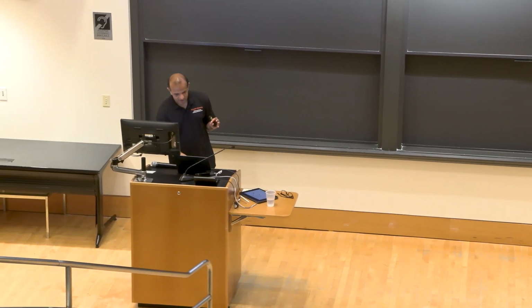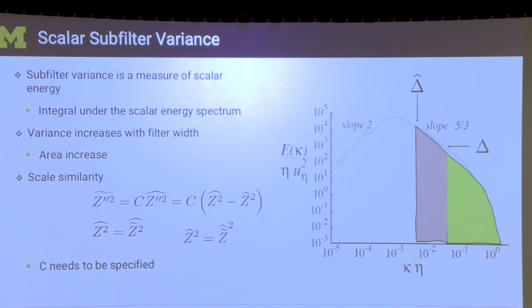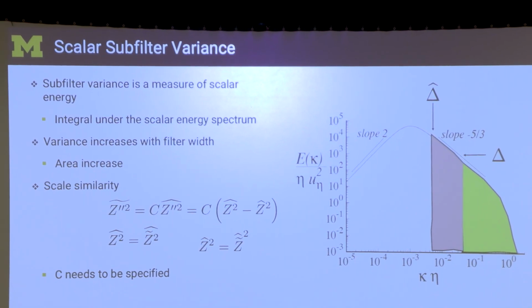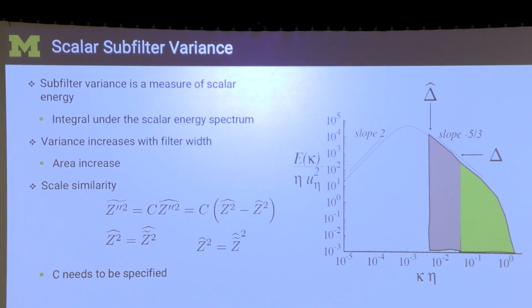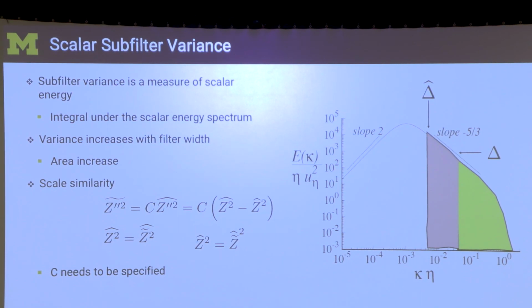So here we use this trick, and this is a very clever trick. When you do LES, and I showed you pictures of it yesterday, LES looks just like DNS, but it's a little bit coarse. It looks a little less turbulent. It's not as chaotic looking as turbulence is, or as DNS is, but it has a lot of different scales in it. So this is the energy spectrum. We discussed this yesterday, minus 5/3 slope here. I have a delta, which is my filter width, and that's this line right here.